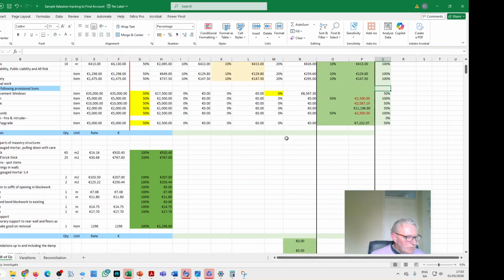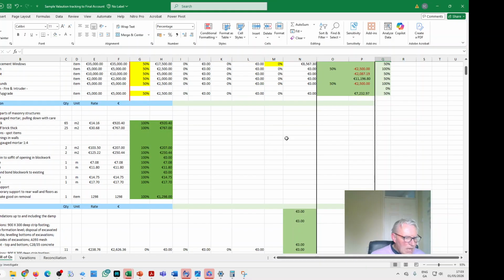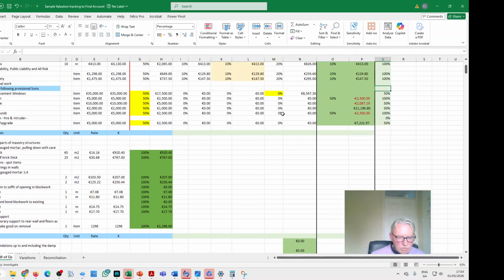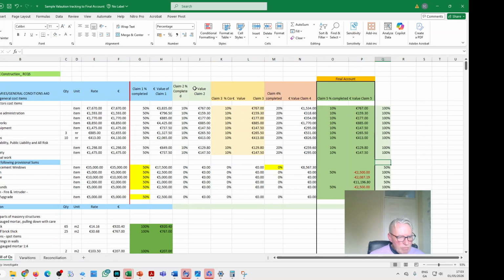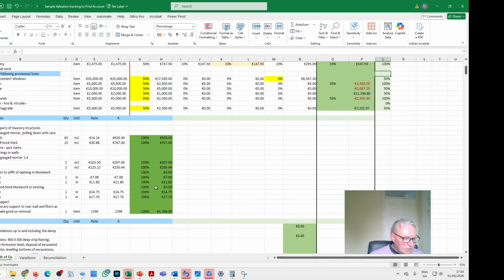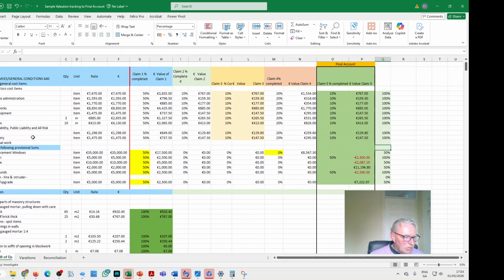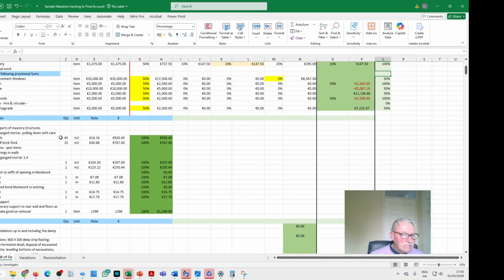And you can see here only 50% of this was done, because the rest of this work was handled elsewhere as a variation, and then this was discounted off. So you need a large screen, you need to do it per month and per activity, and that way you have a cross-reference of activities and timeline, and you can examine this over time. You will also see, as we go down the bill of quantities, that the bill of quantities tends to mirror the stages where construction is done.